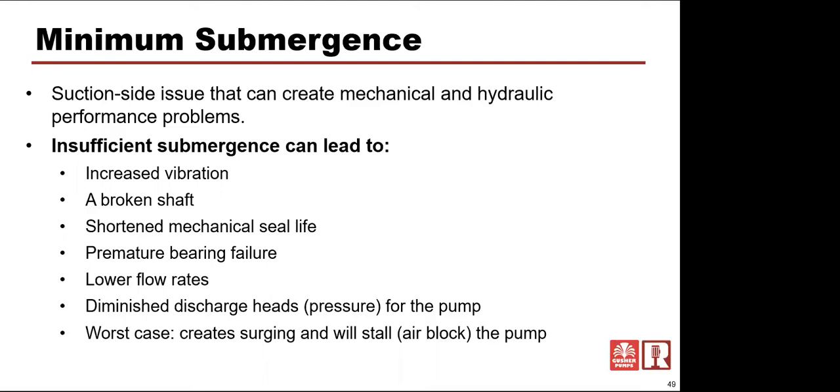So you're going to have an increase of vibration because that air is partially collapsible. Water is basically incompressible. If you compress water by about 0.5%, I believe it goes to about 2,000 PSI. So it's basically incompressible. If you compress air, I think it needs to be compressed about 40 or 50 times to get to about 100 PSI. So it's very spongy, it's very compressible.